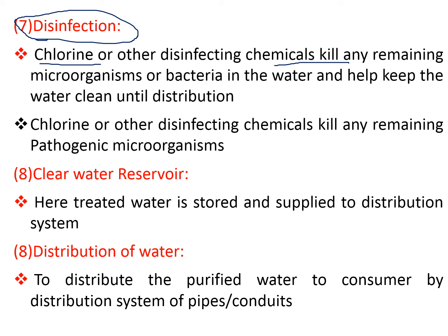which is, once you are giving treatment in the water treatment plant, it has to be supplied to the distribution system. So in the distribution system, if further recontamination takes place, you may not find any chlorine, but it has a good power, that is called the residual chlorine. It will keep it safe against further contamination.